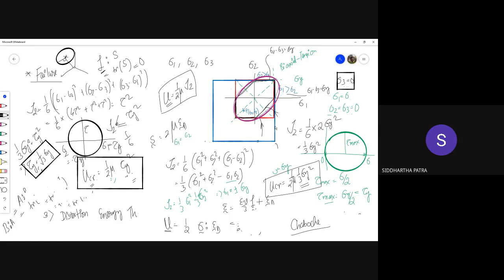The fact that metals conform to the distortion energy theory is a blessing for us, because it is a smooth surface, always differentiable everywhere, unlike the Tresca theory, which is not differentiable at any of the corners. Why do we need to differentiate the surface? We'll learn that in the coming classes, but we need to do that very often. So with that we know how the distortion energy theory can be used as a smooth surface for metal plasticity.